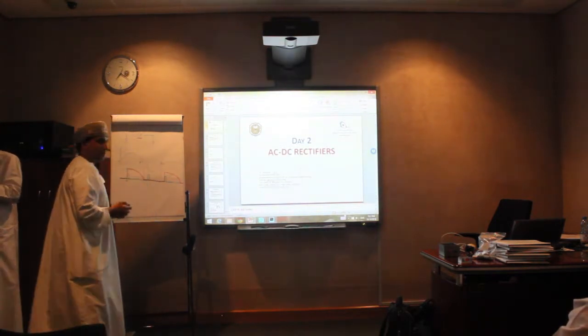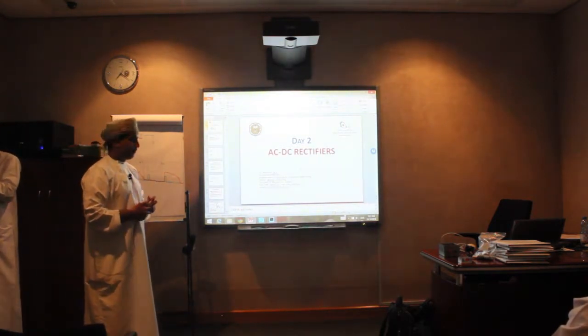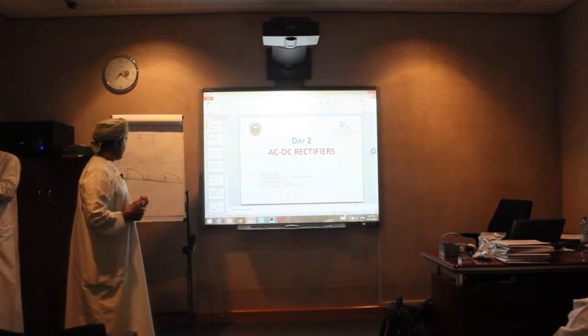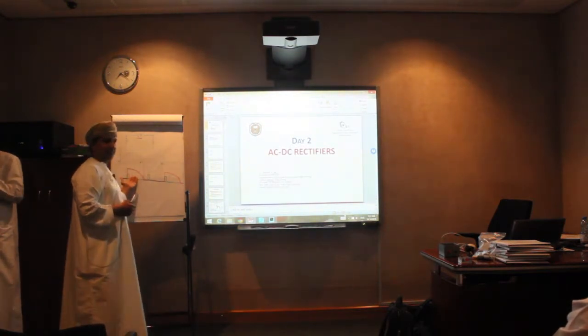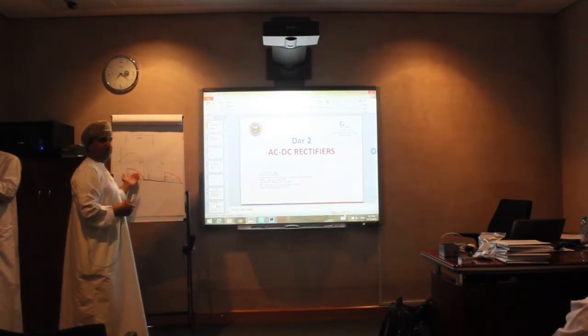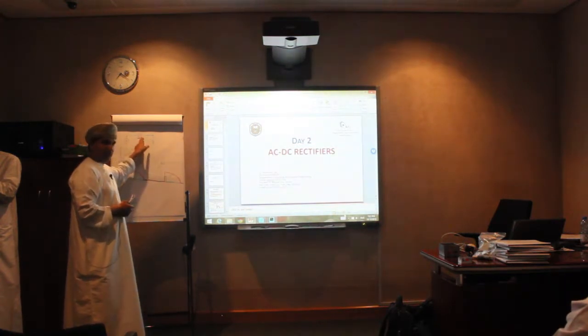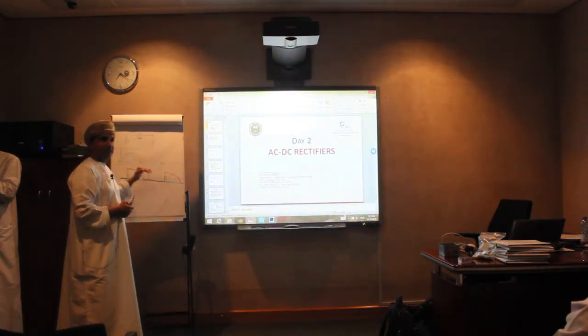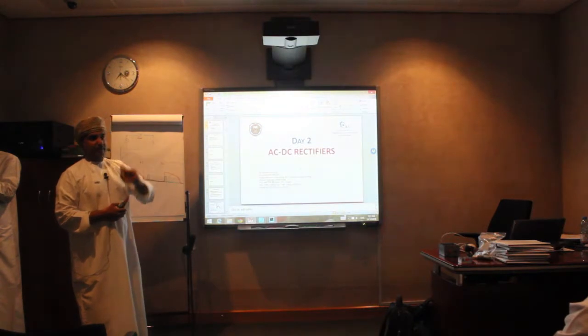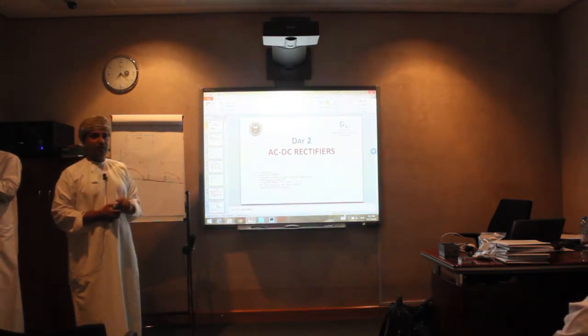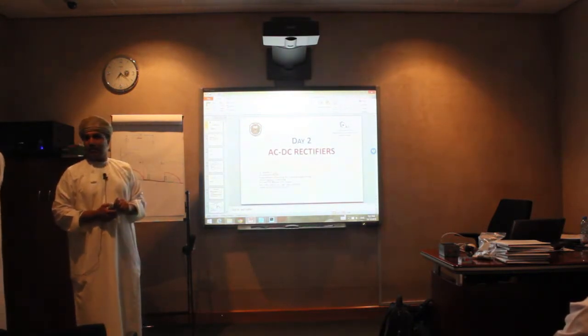I think it can be used also for AC motors, to control the speed of AC motors. No, because the output now is DC. No, I mean the thyristor. Yes, you can use it as part of the driver to control an AC motor. You can use the thyristor to control the AC, but not like a rectifier, like a regulator. You can put thyristors back to back, and you can control the AC output. Exactly.